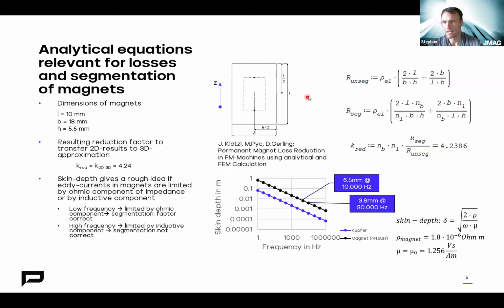In the end, the idea is, if you have a 2D simulation, the upper path and the lower path of the eddy current is not existing, or is very small compared to the actual component. As we have seen two slides before, in a 2D simulation, we can only consider a current density in the actual component, so let's say here in the length of L.